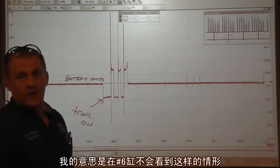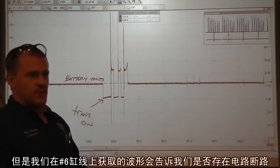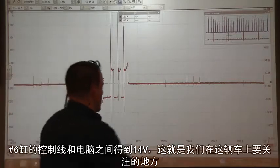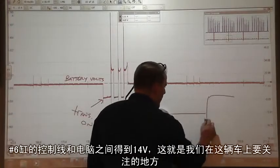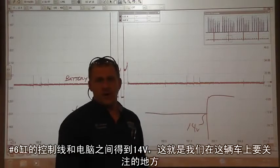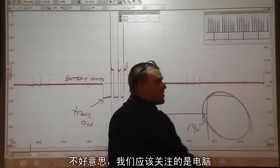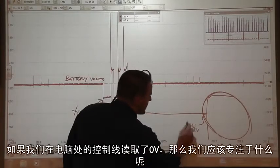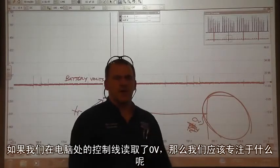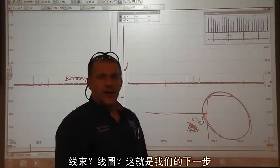We know we're not going to see that on the number 6. But what we have on that number 6 wire is going to tell us whether we have an open in the circuit or whether we're going to focus at the computer. If we go to that number 6 control wire at the computer and we read 14 volts, where is our focus going to be on this truck? Our focus goes to the computer. If we read 0 volts on this control wire at the computer, where does our focus go? Harness, coil. It's an easy check. That's where we're going next.